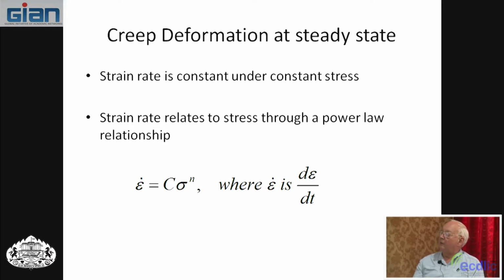So here's the analogy. The creep rate can be calculated through a power law. The dot on top means the derivative with respect to time. That's a general mathematics symbol: you put a dot on top of a thing, meaning you take the first derivative with respect to time. So a coefficient times stress to an exponent is what you do for creep rate in region 2.